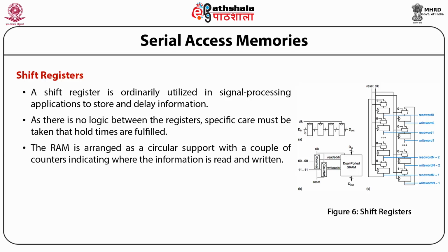The RAM is arranged as a circular buffer with a couple of counters indicating where the information is read and written. The read counter is set to the first entry and the write counter to the last entry on reset as shown in figure B.